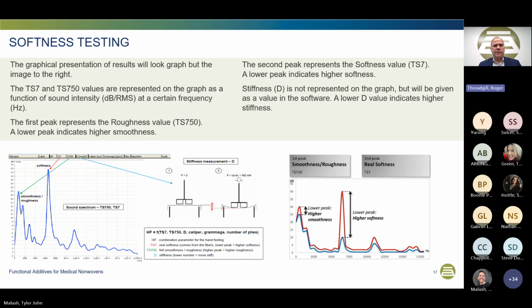So there are different facets to softness: slickness, friction, drape, crush, and like we mentioned before, cotton-like versus synthetic are all ways we can experience tactile qualities. And one of the newer methodologies is the use of acoustic intensity. When you spin a controlled disc or rub it over the specimen, you measure the sound emitted at different frequencies to get a sense of how soft this material should be based on the sound it's generating.